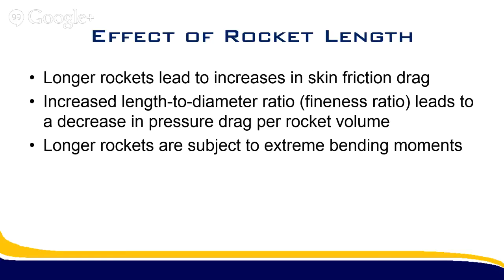They've got quite a curve to them, and if you don't take that into consideration, you may end up snapping the rocket in half, and then the whole flight ruins itself. So I'm not trying to scare you away from really long rockets. Most things that you build are probably going to be completely capable of handling the moments that they're given. But if you have a 3-inch diameter rocket, don't try and build it 9 feet tall. You're setting yourself up for an interesting situation where you may not get that rocket back in one piece.